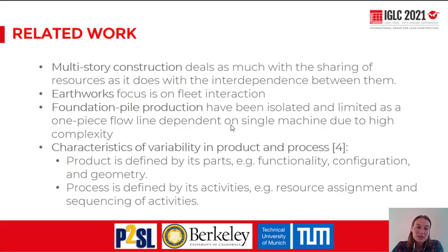When we look at multi-story construction, there the crane operations are important when trying to design work standards to reduce variabilities. So they are the pacemakers. They are largely responsible for material flow and are used by many stakeholders on site. On the other side, we have the earthworks, which are more focusing on the interaction between the equipment, not so much the sharing of the equipment.